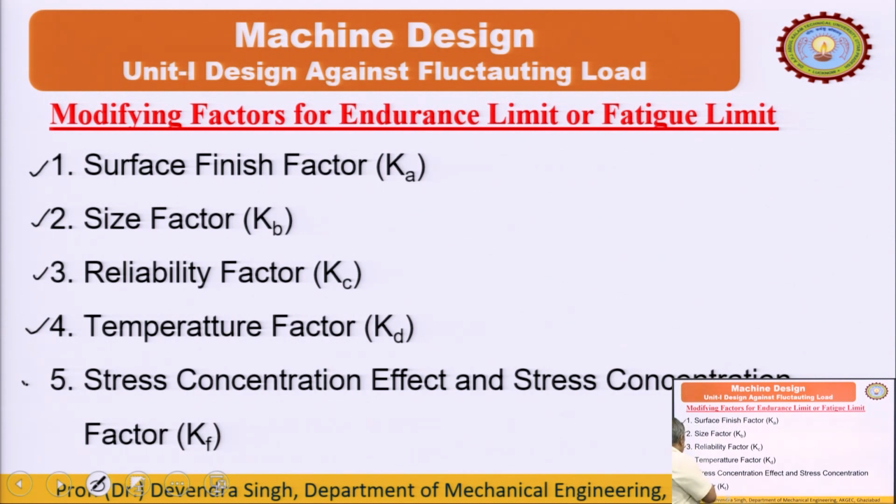This is very important. In fact, surface finish factor, the scratches can be treated as a crack, and if a crack is initiated due to the machining, due to the erroneous or low grade finishing, that may cause fatigue failure. So, we will consider some surface finish factor to modify our endurance strength.